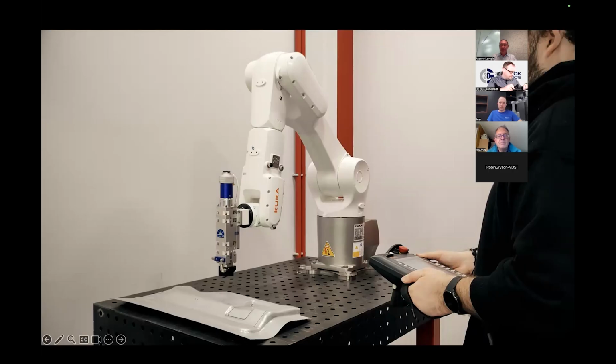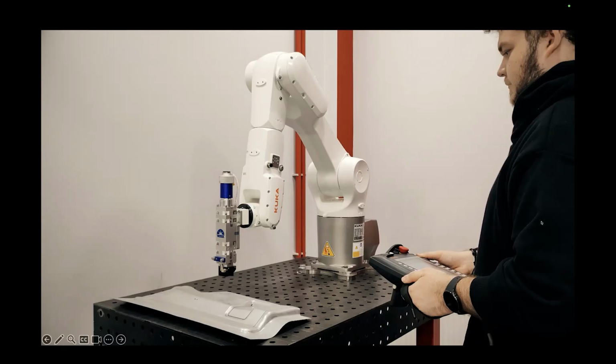First, there is online programming, or manual teaching. The operator moves the robot point by point using a teach pendant. It's simple, it's intuitive, but also very time-consuming. While the operator is programming, the robot stands still and produces nothing. Each new task requires stopping the cell, recording hundreds of points, and hoping everything runs smoothly afterwards.